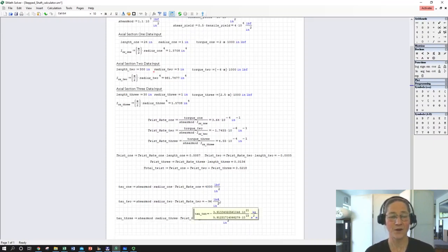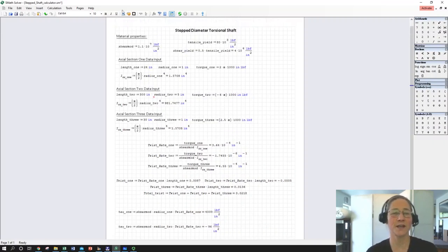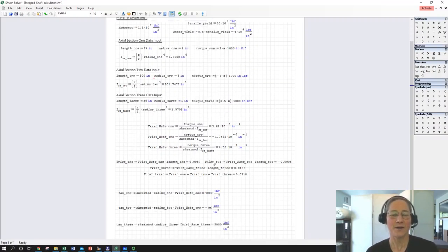Importantly, we also changed our internal shear stress when we changed the radius. Not so much when we changed the length. So the length really only plays in going from twist rate to twist extent, so how many loops around the shaft is twisting. Big changes we might want to make might be things like the applied torque and radius combination.